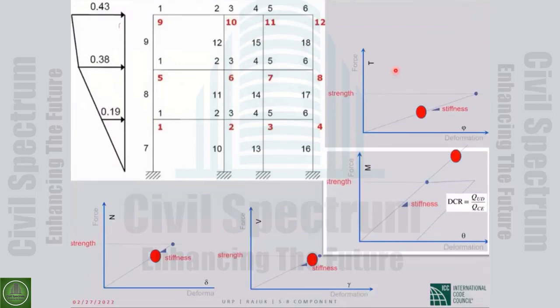Therefore, the linear analysis is not bad. It needs some adjustment because, okay, instead of the real non-linear analysis, we're just doing linear analysis. Now, naturally it needs some adjustment, but it's not generally that bad. So what we do, we model in SAP, whatever software is easier for us, the same as usual.